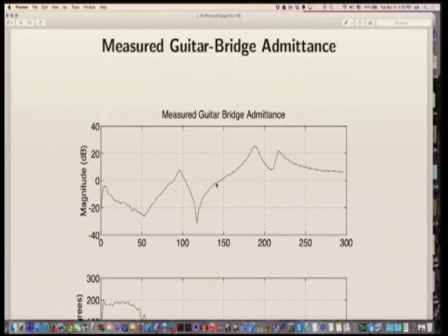And so we see a good measurement of the Helmholtz resonance and 2 plate resonances. And way down here is just, probably, the supports for the experimental apparatus. This low frequency resonance I wouldn't pay much attention to because there's nothing important going on in a guitar at 5 hertz. And so all this low frequency stuff is just stuff we're going to kind of forget about. We're just going to high pass this thing at around 50 hertz and work with the data above that and neglect everything below. Guitar doesn't need anything below 50 hertz, right?